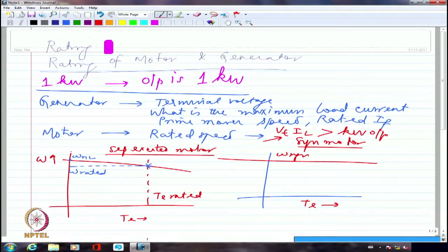You can't do anything. So what is left over is EB multiplied by IA. That is the power developed, minus whatever is the friction and windage losses, if those are given. If those are not given, I would conveniently assume that it is ideal condition, friction and windage losses are 0, if they are not given. Got it?